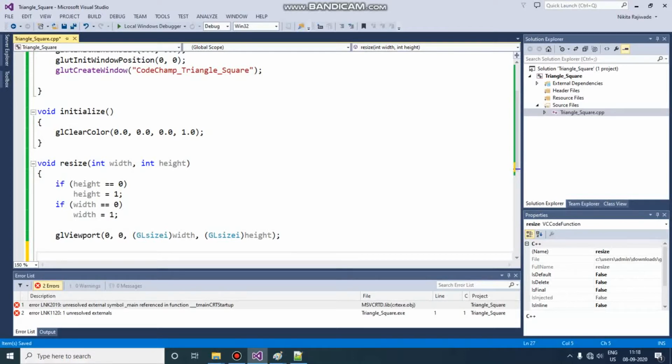There are two types of projections, orthographic and perspective. Orthographic is used when you need to show the object as it is. You don't want to change any measurements. In perspective, you can consider the lines go parallel. Like if you consider a road, you are standing in the middle of the road, and if you look at one end of the road, the two edges of the road appear parallel, but they tend to meet at some point. So this is also called frustum view.